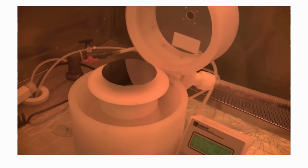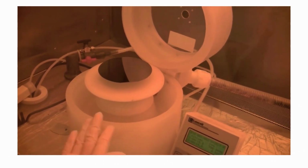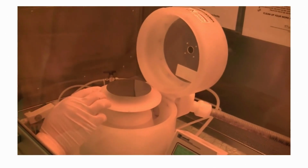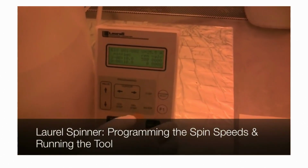I'm not going to say how much you need because that really depends on your photoresist. There's always a manufacturer recommendation, and I would recommend using that volume. It tells you per square centimeter how much volume you need. So once you have that settled, you can close it. Here's where you program it.